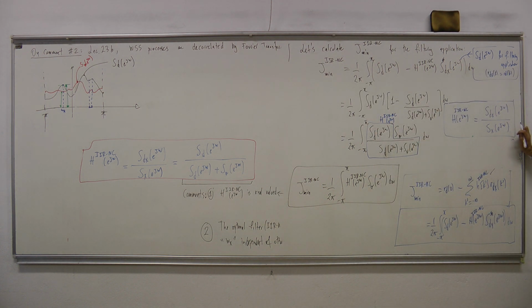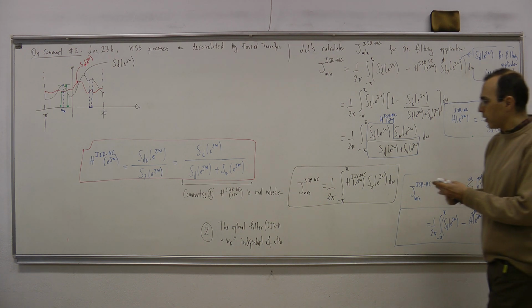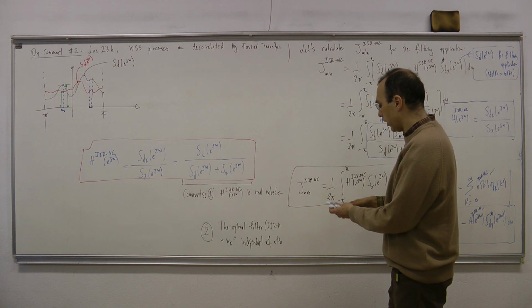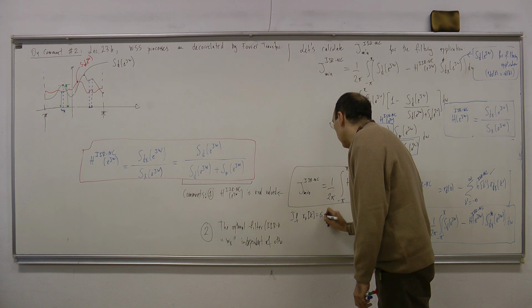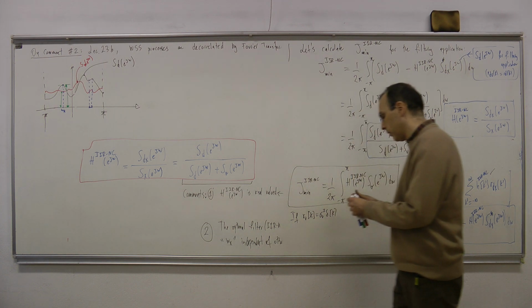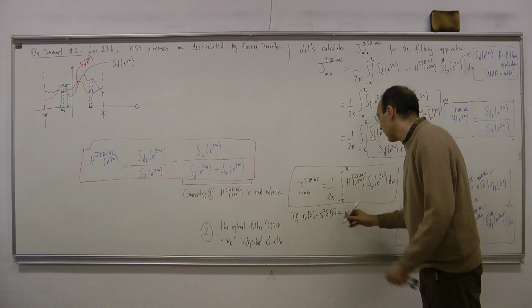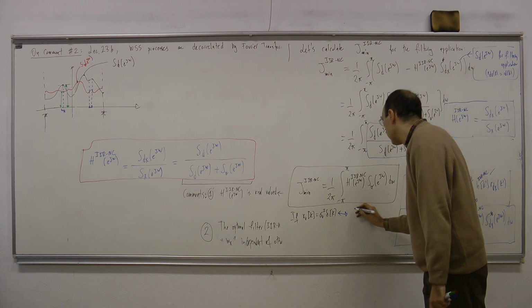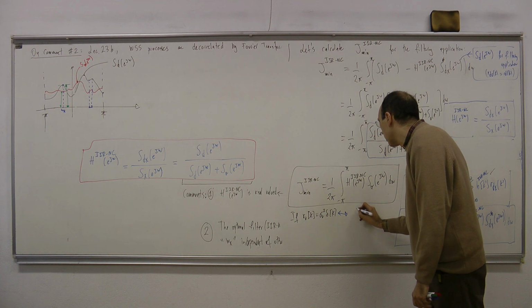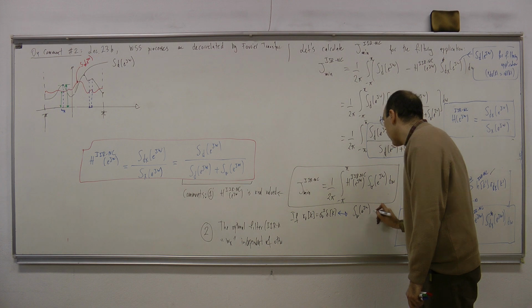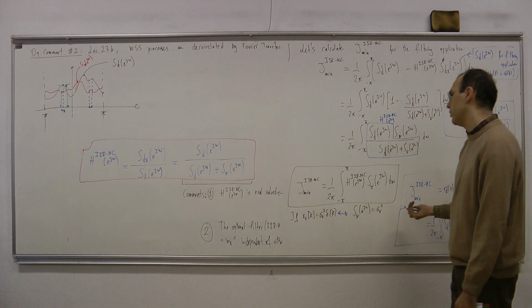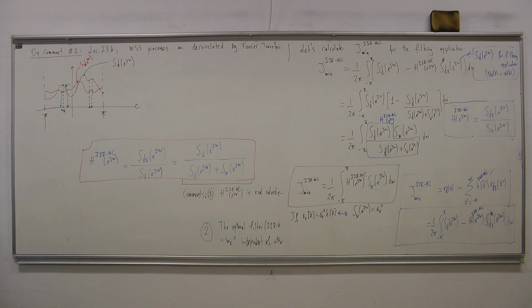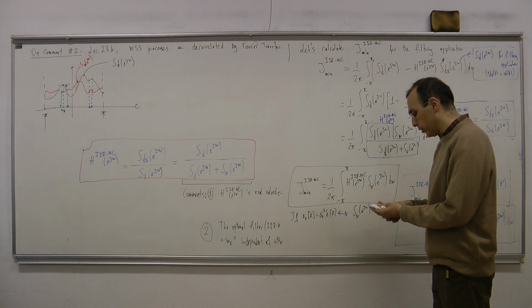Since I'm expressing this filter in the frequency domain, I'm also calculating the error using this frequency domain representation of the filter. Now there is a special case. If Sv is white noise, let me write that. If Rv of k is sigma v square delta k, then its DTFT is Sv of e to the j omega, which is equal to sigma v square. So this is the white noise condition.